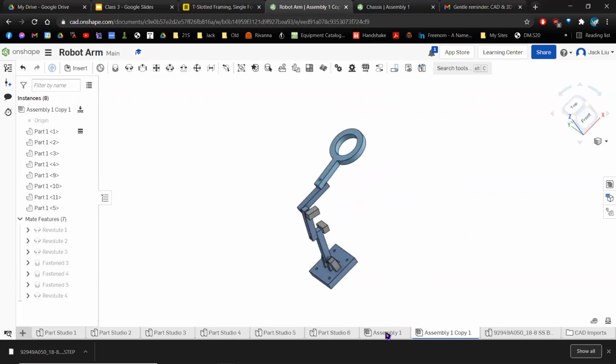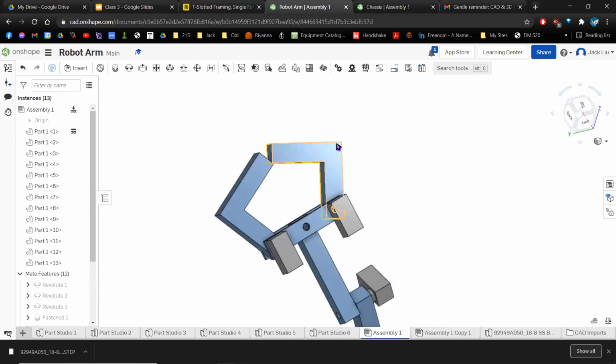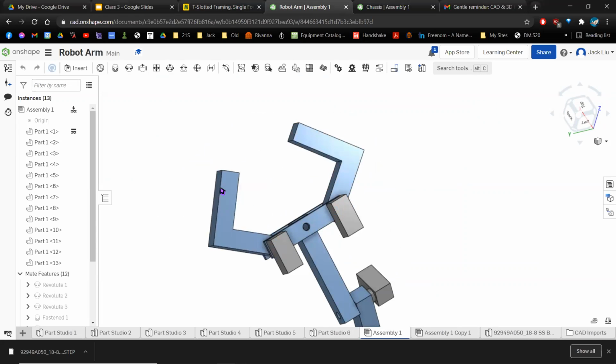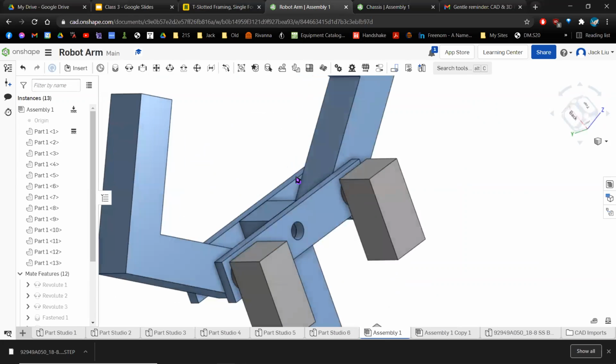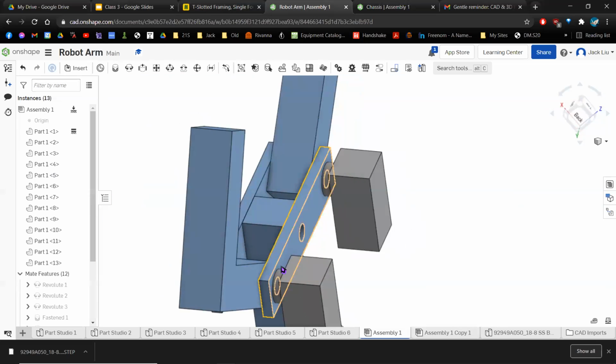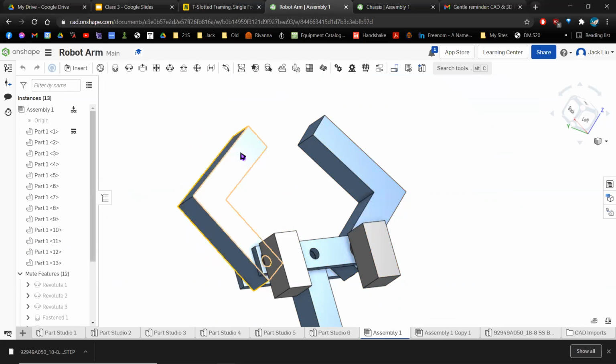You could do the grabber option, which looks like this. For this one, you have to CAD your arms, your fingers, that will go back and forth. And then you also have to find a way to connect it up to your arm. So the way Eugene did it is he had these bars that have a hole to connect to the arm, and then 2 holes to connect to each finger, right? Each of these could be driven with a servo, which is what he has right here. And that would allow it to open and close like that. So again, these are 2 options.